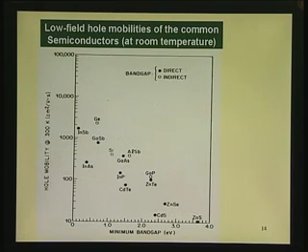So, you have much more flexibility. Now, we have said about electron mobility. I have been silent about the hole mobility. I have been silent because it does not look attractive. You can see here silicon, for example, hole mobility is about 400, 450. Hole mobility for silicon is that. But if you see gallium arsenide, it is lower or almost same. Indium phosphide, it is even lower.